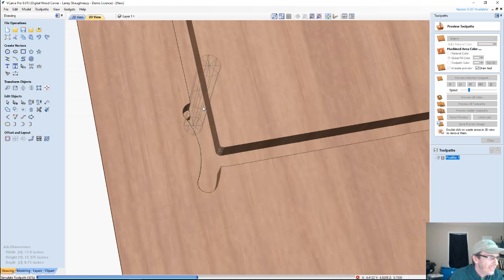And then it's going to lead out away from the cut. It's going to raise up and move to the next lead in. And again, all of these things optimize our workpiece, the result of the end cut and things like that. And they also help with extending the life of our bit. Now, the lead in and lead out and all the leads aren't helping with extending the life of the bit. It's our ramping that does that.